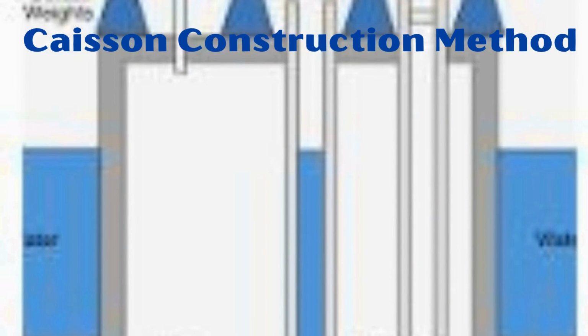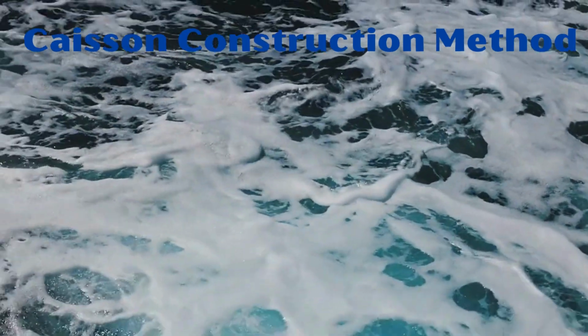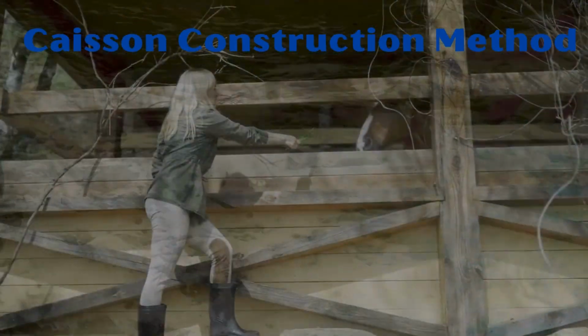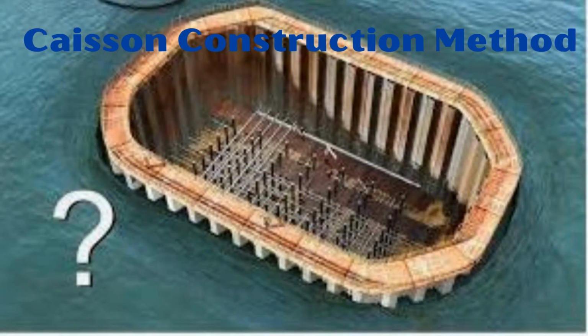2. Box caissons. Description: prefabricated, closed at the bottom and open at the top, floated to the site, then sunk and filled with concrete. Usage: typically used in deep water. Advantages: provides a stable and secure foundation. Disadvantages: heavy and requires precise placement.